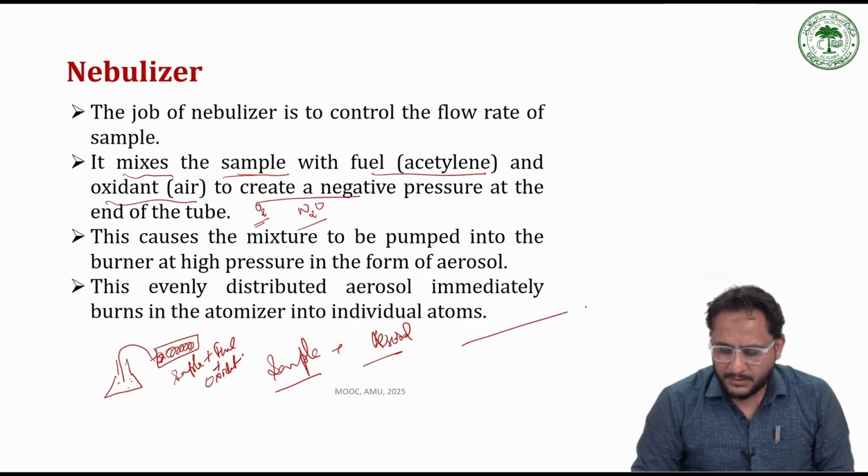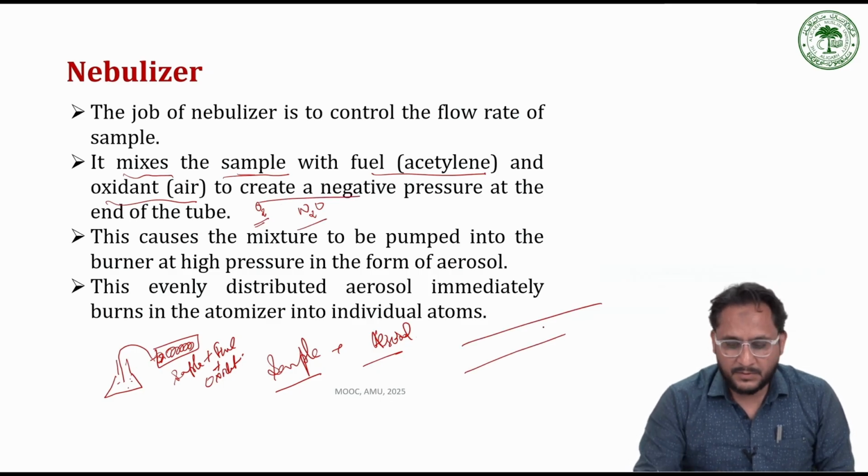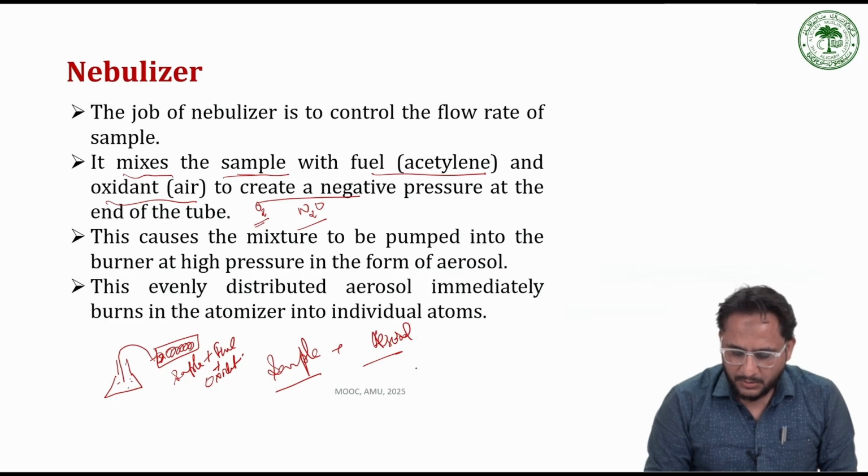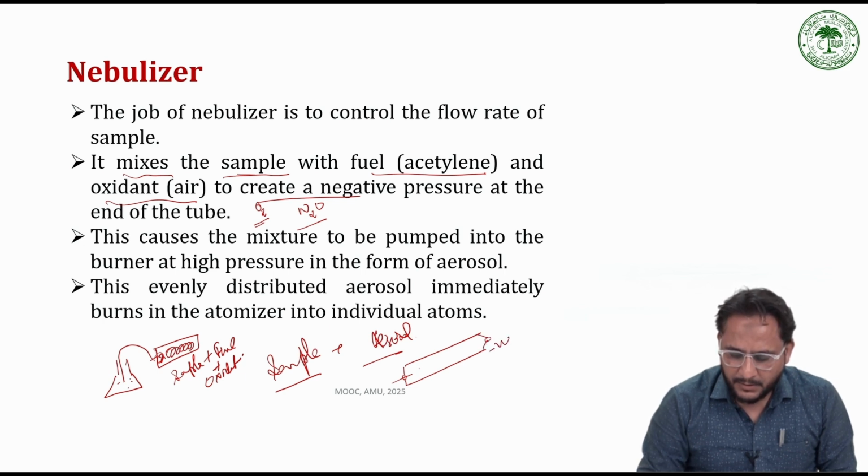Now the nebulizer has a small orifice over here, the sample is injected, and finally when it is released, it creates a negative pressure at the outside of this orifice. When this pressure is negative and we have high pressure over here, then this high pressure will inject the sample